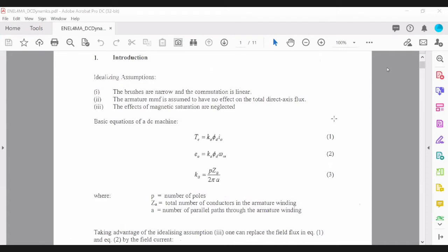the response that you're getting following a certain change in, for example, the torque, will basically affect the speed of the motor. And so we will derive the transfer function and look at, for example, your damping ratio and the natural undamped frequency of the system. All that we can basically represent in the S domain.